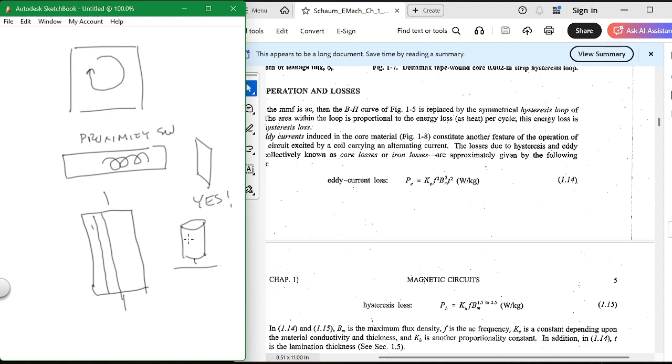We can even do that with this. You have it spinning to the left or counterclockwise. Take any two leads, turn them around, in other words flip them, and it'll spin the other way. And you don't believe that? We'll try it. It'll work. You'll see it, okay? We're going to set that up upstairs. Not today, but one of these days. I don't know if it'll be during lab or during lecture, but you'll actually see that happen.